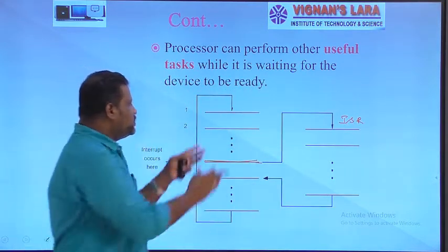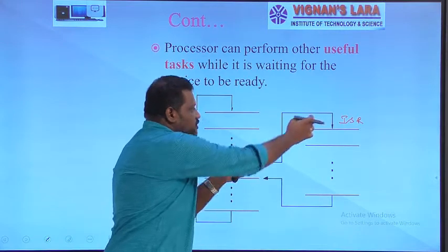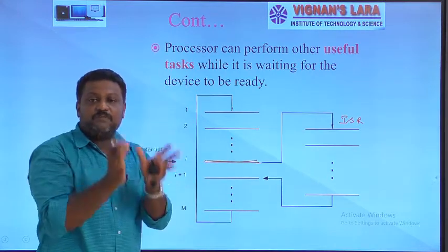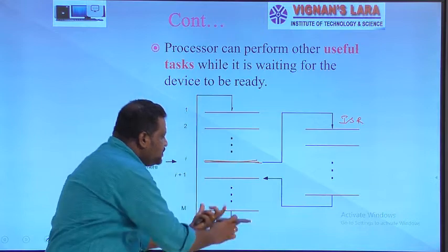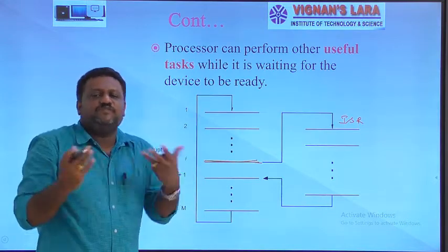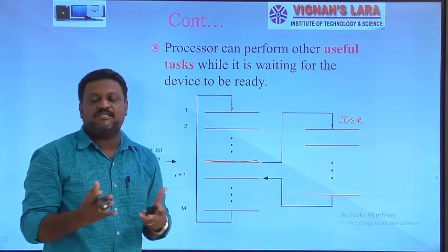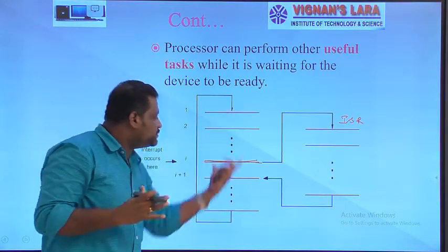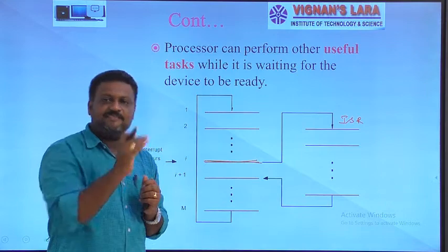Before shifting our execution from this particular instruction to the ISR, our CPU has to preserve this executing program's information in the stack. Which information can we store? What is the necessity to store the information of this program on the stack?